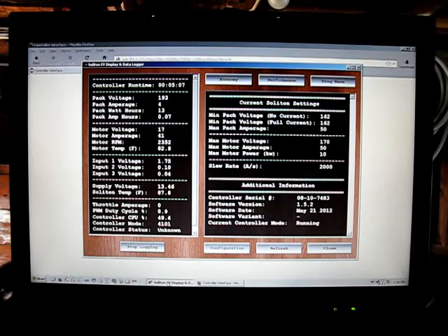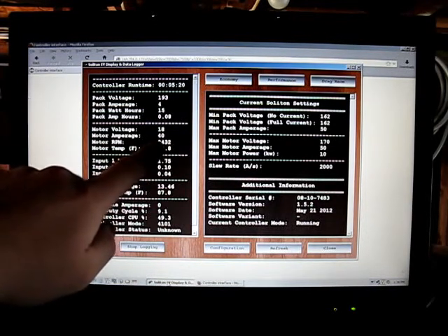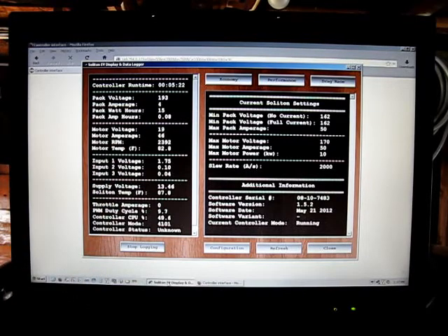So we're pulling a lot higher voltage. And interestingly, and I guess not so surprisingly, we're pulling less amperage. So it's hovering between 18 and 40 amps and kind of jumping around in there, whereas the motor voltage is pushing up from 6 to 20, whereas before it was capping out well under 10.